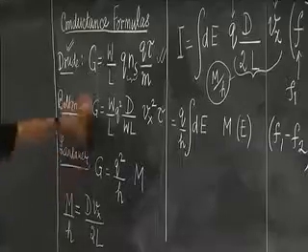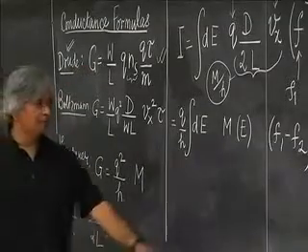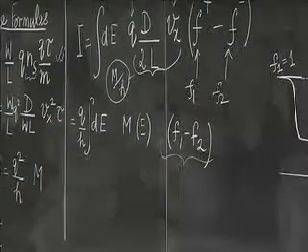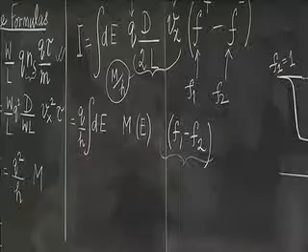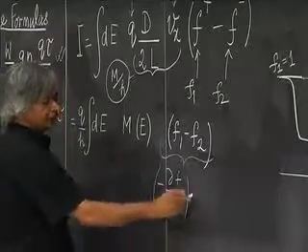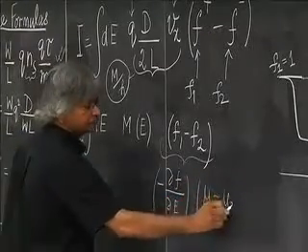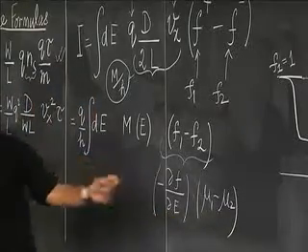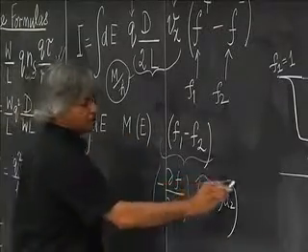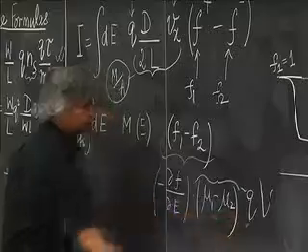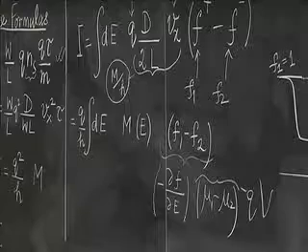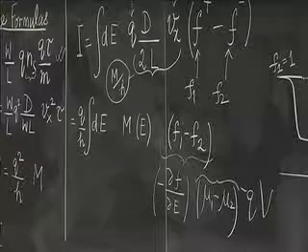Okay. Now, how do you get to this conductance formula? Well, that's where basically what you do is this F1 minus F2. For low bias, we say that we are taking the difference between 2 Fermi functions, and you could write it as this Taylor series type of thing, del F del E times mu1 minus mu2. And this integral dE minus del F del E and this M of E, and mu1 minus mu2 is Q times the voltage. And so current becomes proportional to voltage, and whatever's inside, that's then like the conductance. This would be the standard derivation of the ballistic formula.